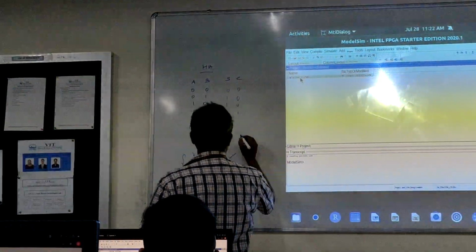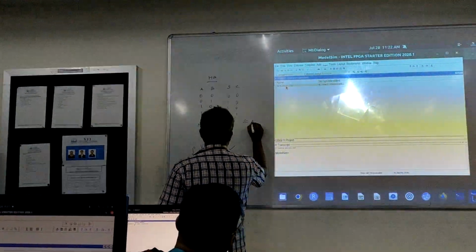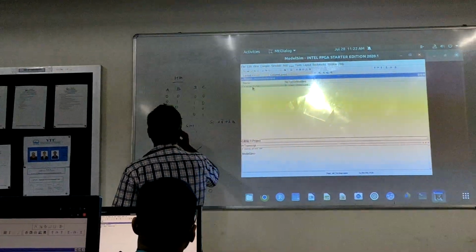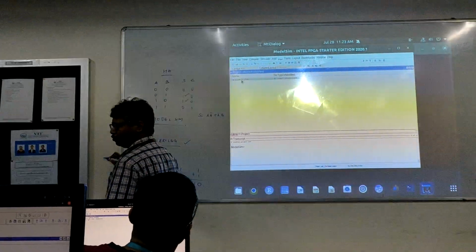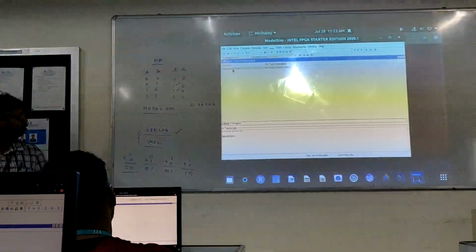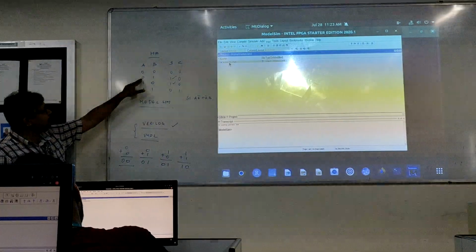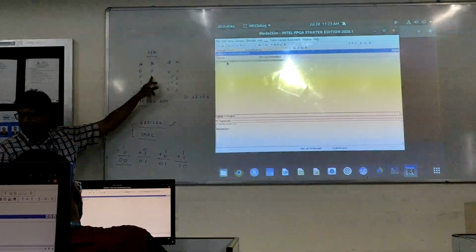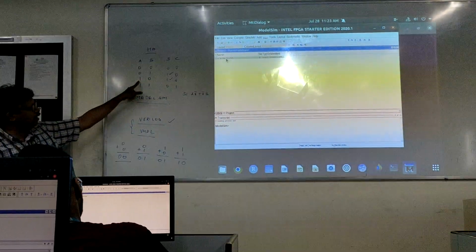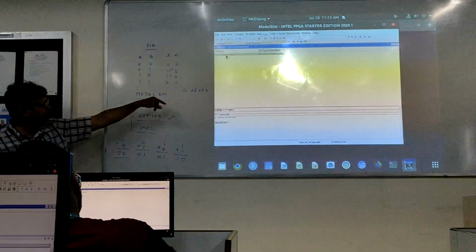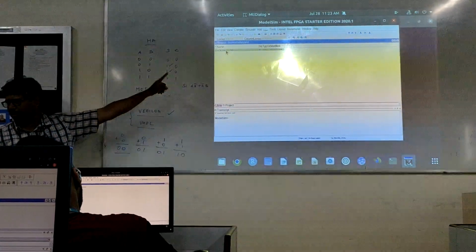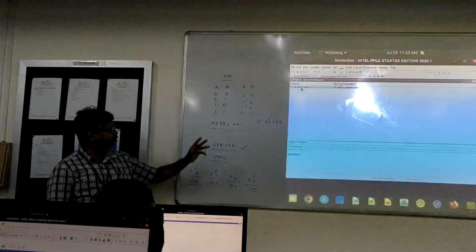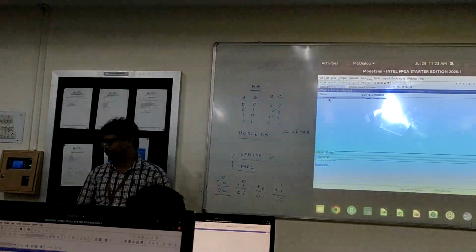So the expression for sum is A B bar plus A bar B. So how have you taken it, sir? Take this form. What is the value here for A? It is 0, so write A bar. This is B, write B. Next here the value for A is 1, therefore you write A. Value for B is 0, so write B bar. That is summation, the SOP form. POS form means you have to group with zeros.